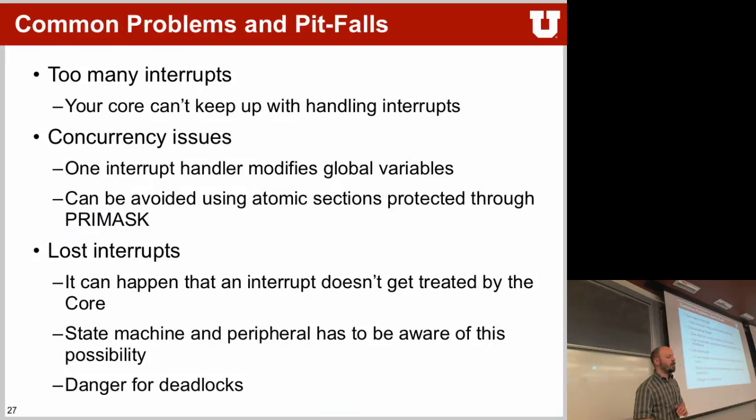Okay, a couple of very common pitfalls that can happen. If you generate way too many interrupts, you can overrun your code, and you will just always be stuck in an interrupt handler, and you will never execute your main code anymore, right? If you just keep generating the same interrupt way too fast, and your interrupt handler didn't have time to execute an exit, it will just tail chain the next one and the next one and the next one. You're stuck in your interrupt handler.